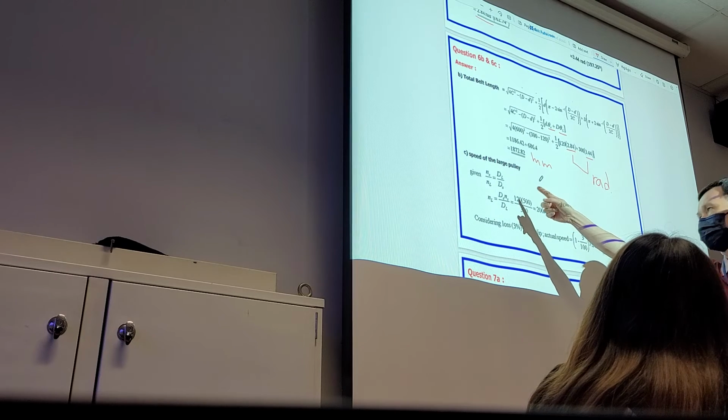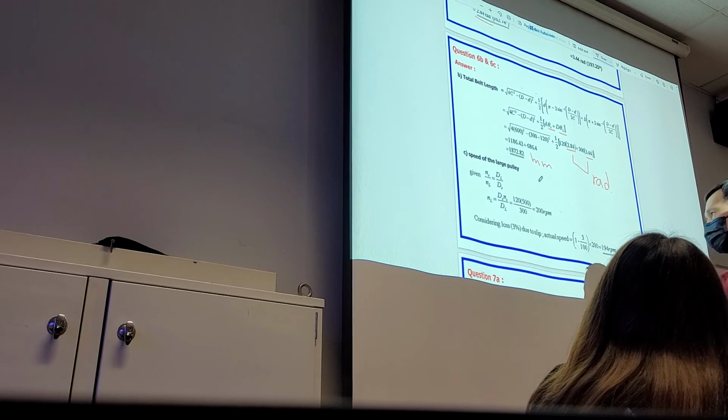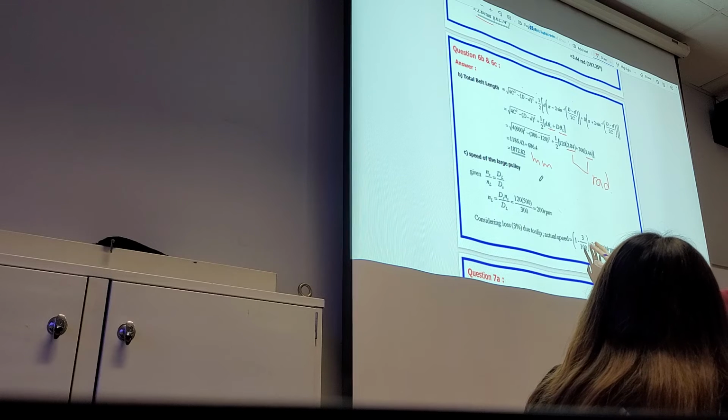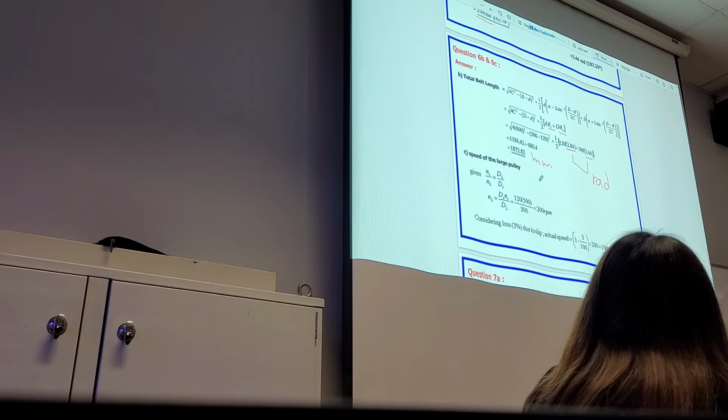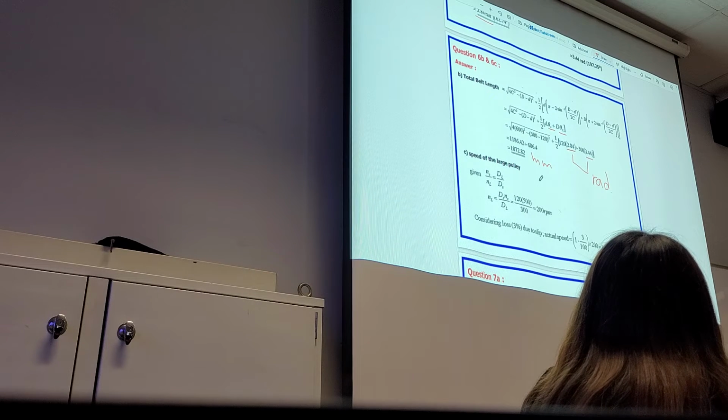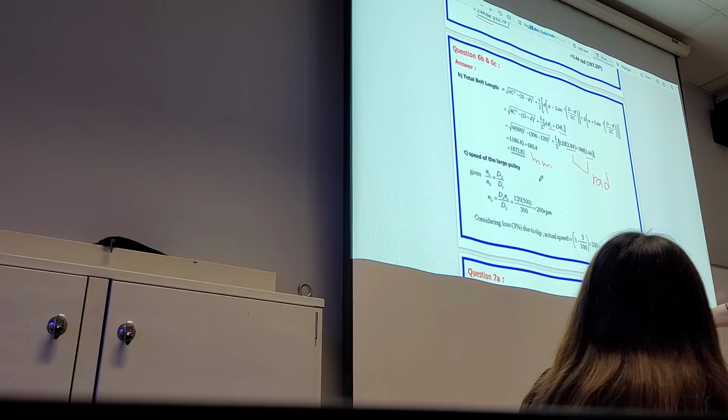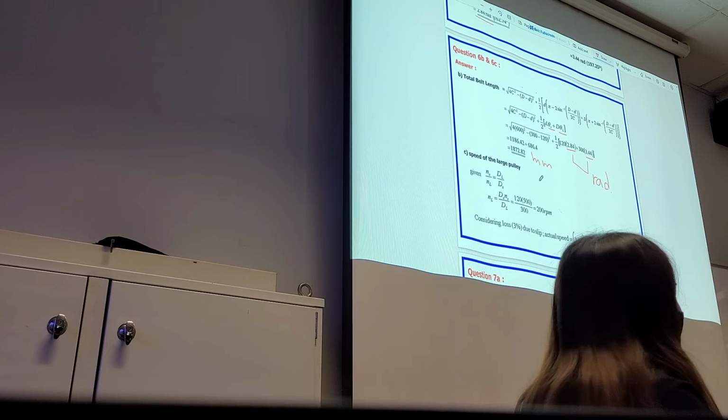So once you have this correct formula, then you get the answer correct. And sometimes you will consider 3% speed loss, because a belt drive is not a positive drive. It's based on the friction. So during the drive, certain speed will be lost. So you just discount by 3%. Actual speed is around 1.4, something like this. So calculation wise, quite straightforward.